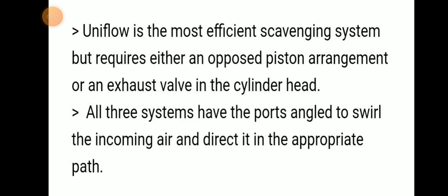Uniflow is the most efficient scavenging method, but requires either an opposed piston arrangement or an exhaust valve in the cylinder head. And in all the systems, the ports are angled to swirl the incoming air and direct it to the appropriate path. Thank you.